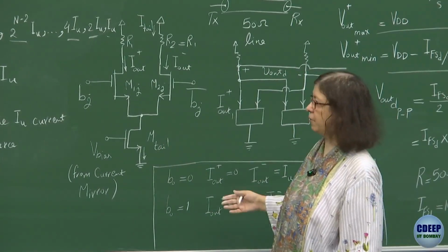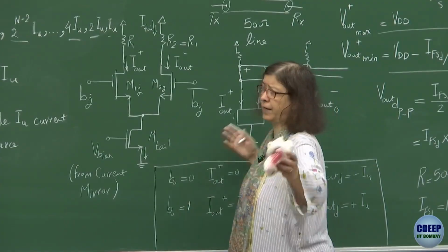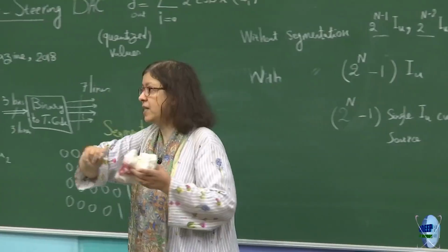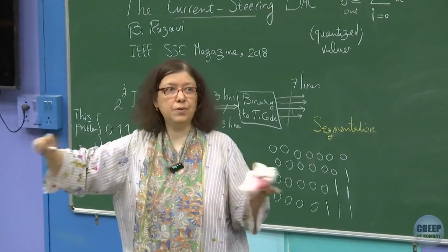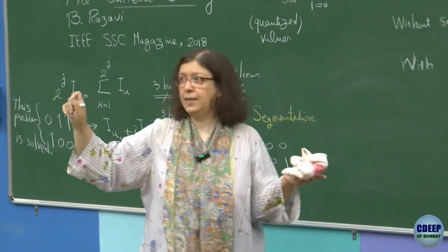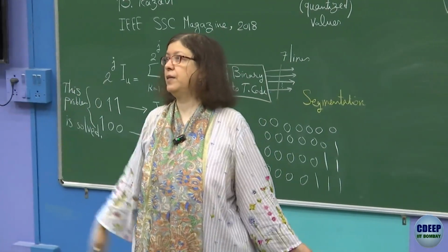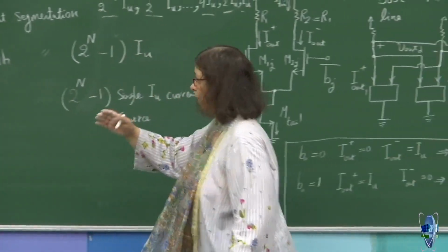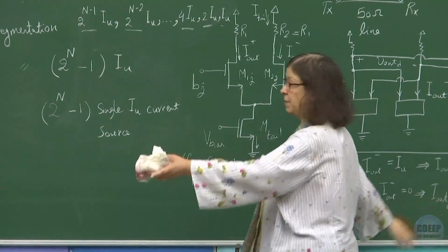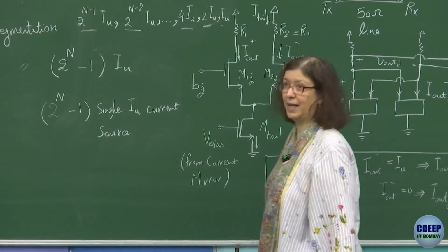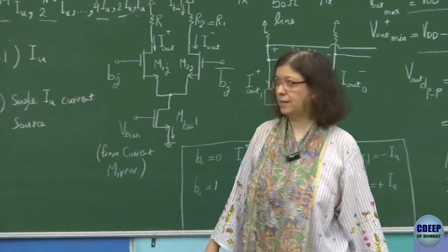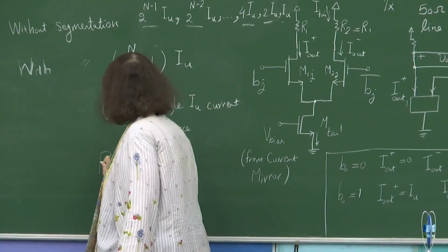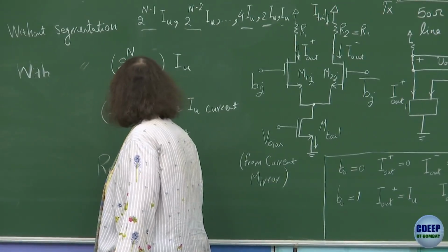So now that will go away, but now we have a very long layout. Again, it is very important. And as we discussed at the beginning, too many interconnects also at the output, at the ground level, at the VDD level. We have to take care of the series resistance, because imagine that ground has to go all the way from left to right. How much would be the effective resistance of such a long line? So that's why routing is very important, and it should be taken care of.